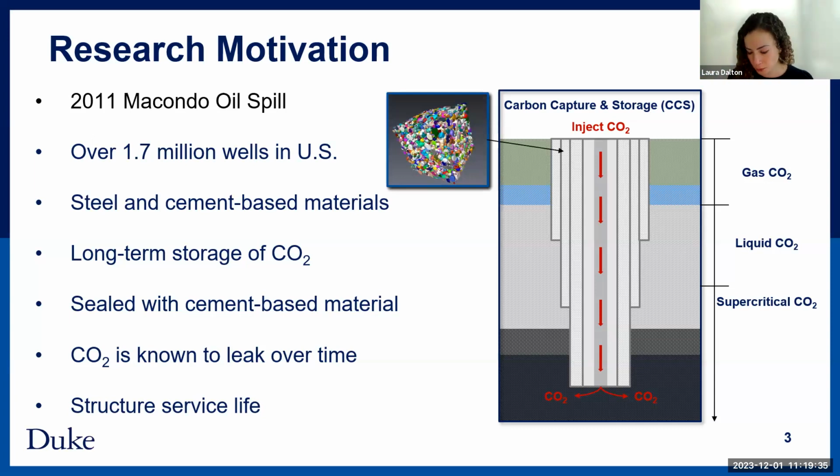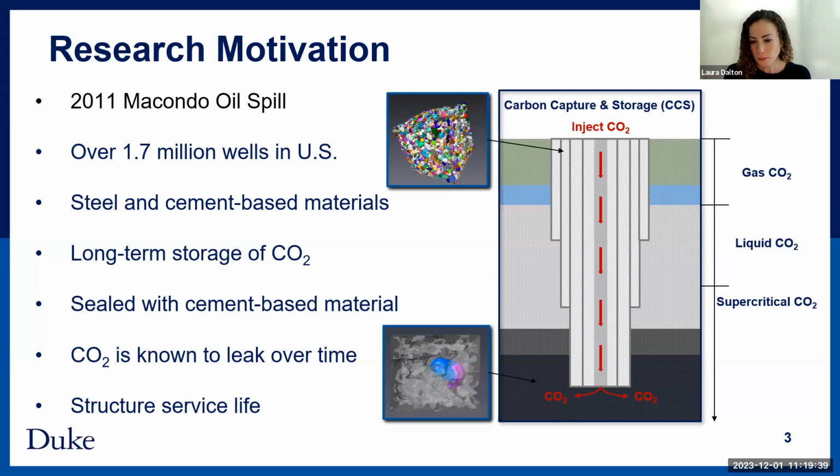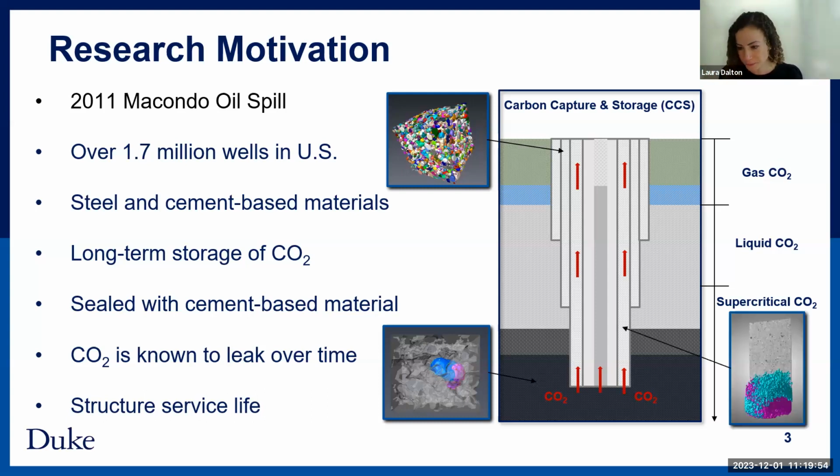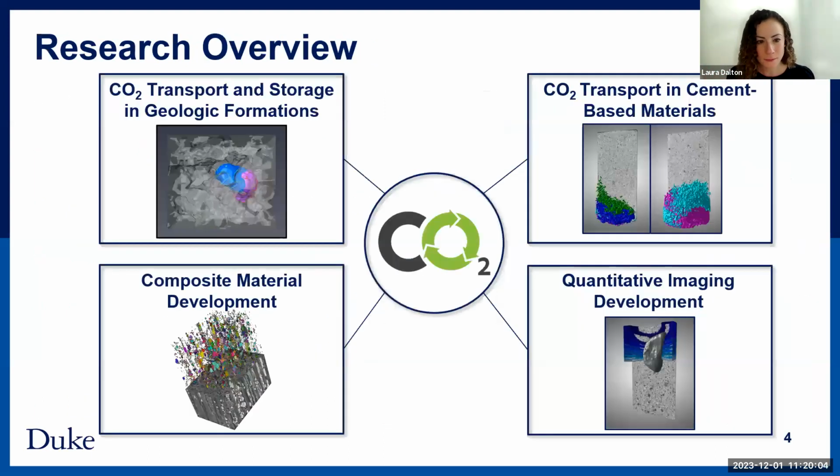They're made with foam cement, some of them offshore and on the wells. Right, we'll store CO2 in the ground, and that's really what these images are depicting. We'll plug these wells, but in reality, to some extent, we can have some leakage back into these structures, which could compromise the structural service life, especially when you have supercritical CO2, because it's a whole different beast when you transition from gas liquid to supercritical CO2, and we'll talk about that more.